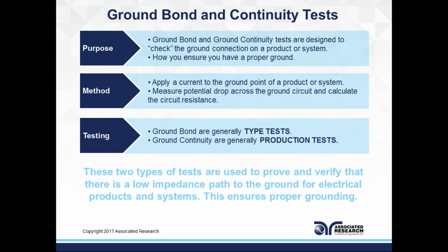Now, if someone made a change, say you designed a product with a particular wire gauge during your design phase, but when you go to production, somebody bought a different line cord, for instance. As application engineers, we run into these calls where customers use our equipment and ran all their tests during prototype phases. Everything was passing for ground bond, ACW, HiPot, and all that. Then when they go to production, now they're not passing anymore. It turned out that in the end, they had bought some cheap line cords, which were not part of the design when they first designed it.